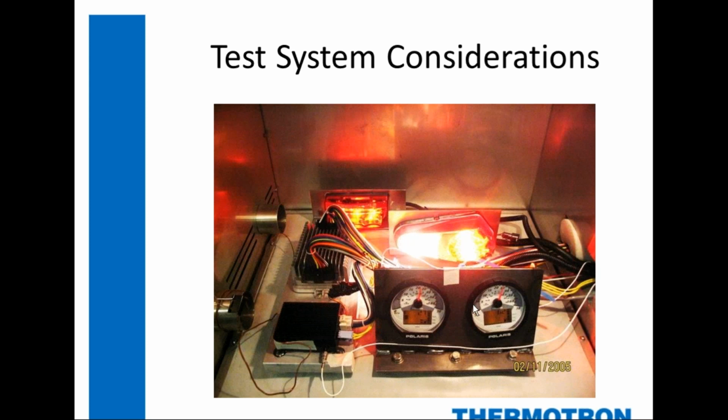So you'll see the gauges are active here, the lights are on, and the reason for that is so many of the failures that we find in the lab, and also our customers find, or your customers find, only occur while they're being stressed. If you're just simply placing a product in a chamber and not operating it during the test, you miss a lot of those intermittent failures or failures that only occur while they're being stressed.